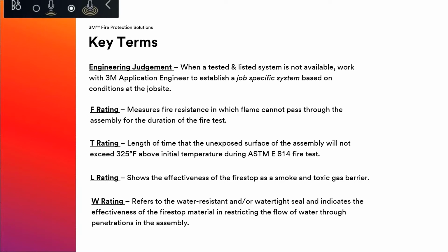So again, some key terms or criteria when referencing firestop systems are your F rating, your T rating, your L rating, your W rating. And again, not just the product is going to provide you these ratings, but the system. The system's going to detail if these ratings are achieved. And then again, as I mentioned, if you do not have a system that you can install to, then get with the manufacturer of the material that you're using and get an engineering judgment for your exact condition that you have out on site.